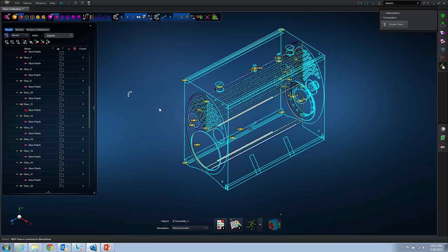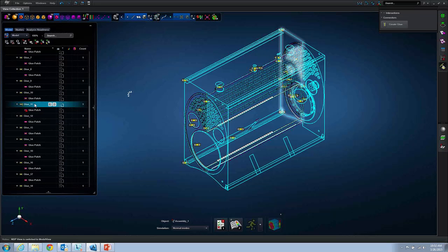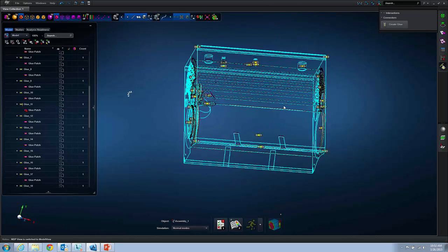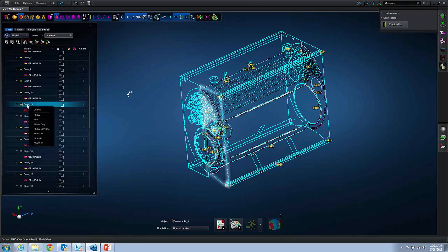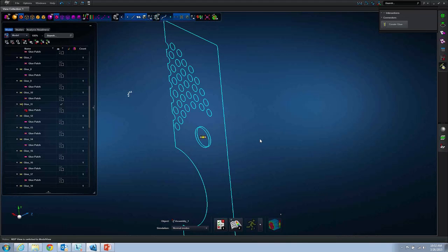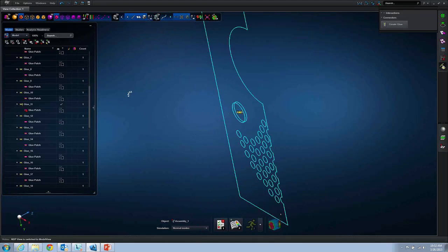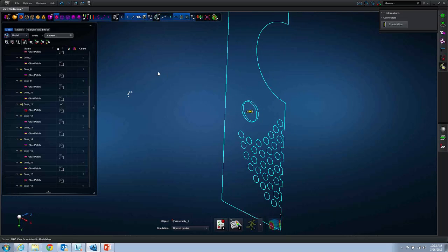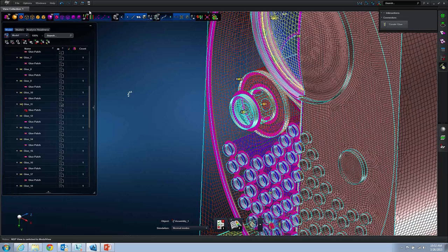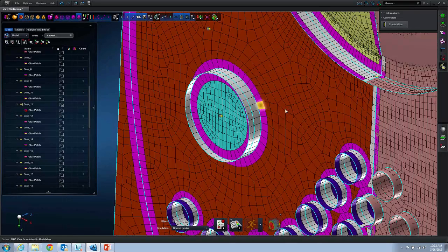That implies that it did create a pair with a given tolerance, but it did not create a patch. Let's look at only that one, and that is the area. And now let's show all, and maybe highlight this one. If you notice here, the blue part is to be connected to this red one based on the pair, but certainly there is a bigger gap there and it did not find a patch, and therefore that became an empty glue, and therefore it is not ready to run.